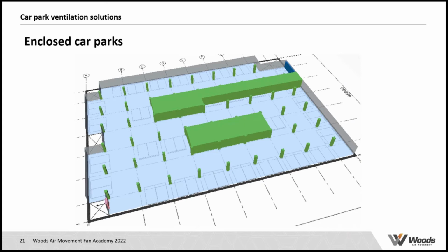And let's utilize the entrance ramp as our fresh air supply, which, if it's a single level car park, is possible because mostly those entrances are open, or you could make them at least partly open by using an open roller shutter, and get the fresh air in naturally instead of mechanically. That's our first saving already. If we can utilize the entrance ramp, we don't need mechanical supply fans, which is obviously a cost saving, and certainly an operational cost saving in the longer run.